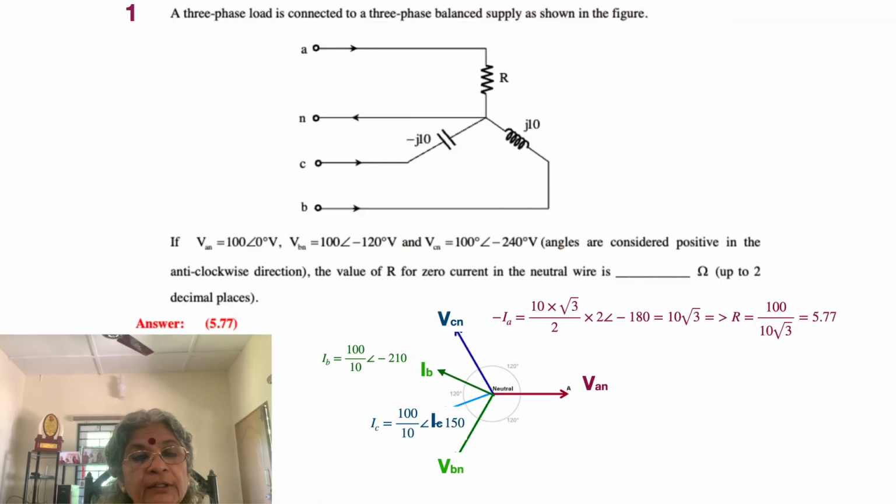So now we have these two currents in the second and third quadrant, of equal magnitude, such that their imaginary values cancel. So it's only the real quantity which has to be cancelled by the current carried through phase A. What is it equal to? It's equal to the sum of the two currents, because it's in the negative direction. That's the reason why we see that our IA or minus IA is the same as the sum of those two currents.